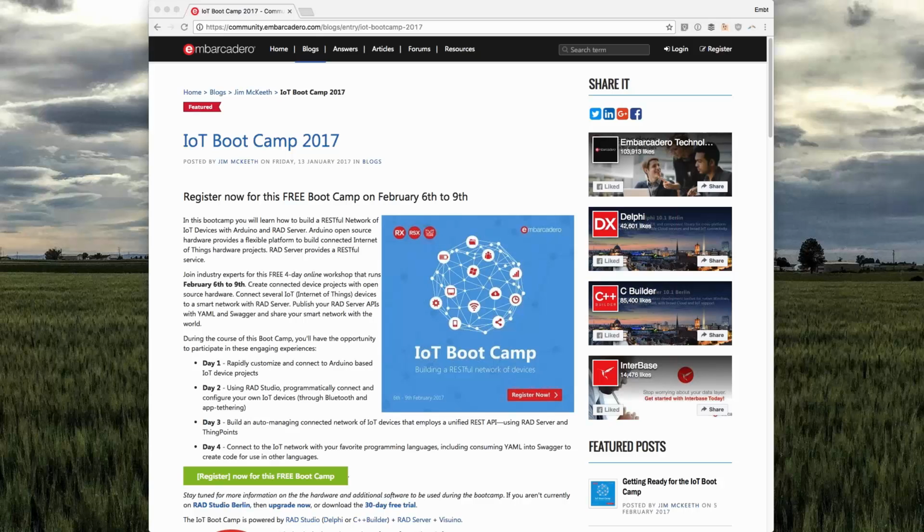Well, the easiest solution, if you're not very experienced with power and stuff like that and just want to play, I personally play with it by using a USB power bank. So the easiest solution is to use a USB power bank, and then you can get separate rechargeable batteries. They were considering adding that into the kit, but I suggested not to do that, to keep the price of the kit as low as possible. You can just use a normal battery, like a 9-volt battery or something, and hook it into the Arduino and power it with it.